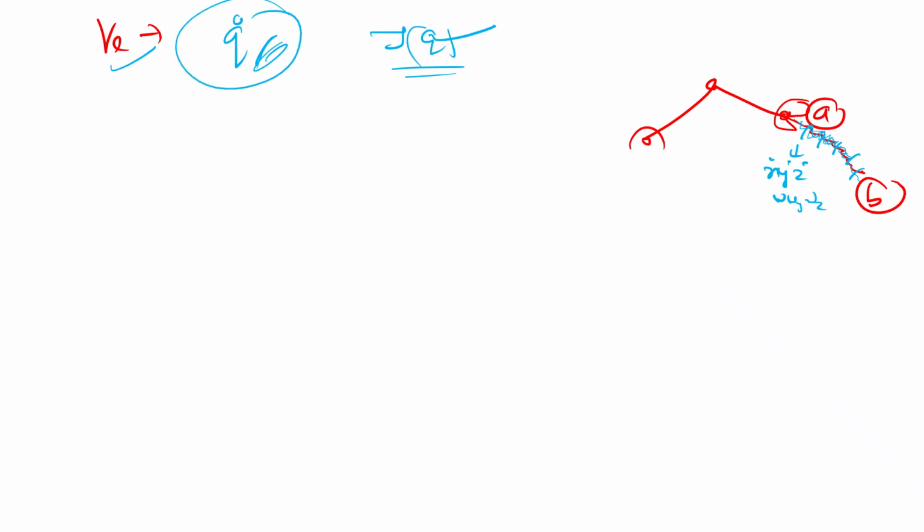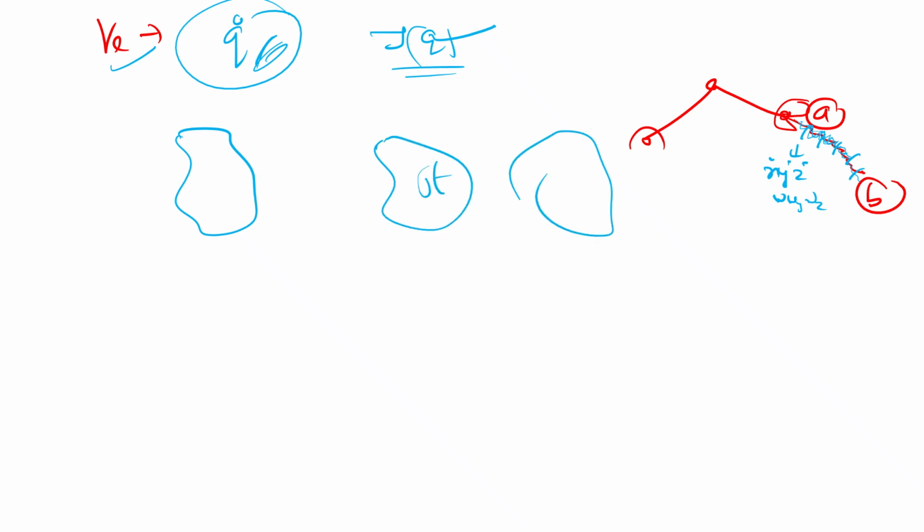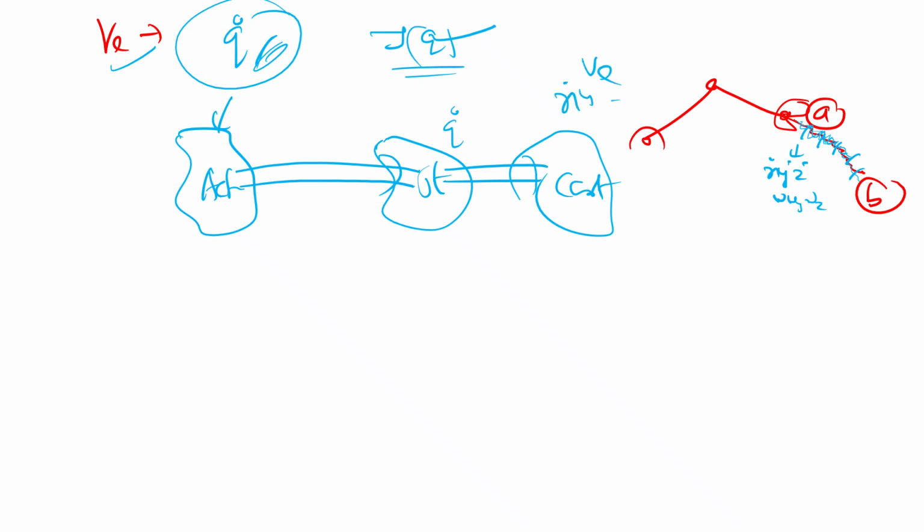Okay, so I can say that here is some mapping. Okay, so this is joint space, and then this is Cartesian space. This is actuator space. Okay. So first, the user says, I need this kind of velocity. Okay, so that velocity is given as a control input to the actuator. So as a result, the actuator gives the joint velocity. Then that joint velocity is converted into an end effector velocity, x dot, y dot, like that. Okay, so this is the mapping. Okay, so let's move to the problem.